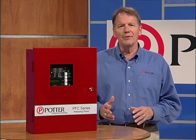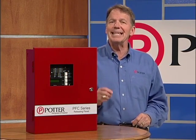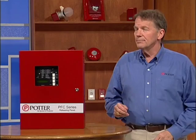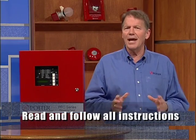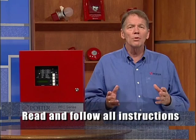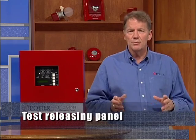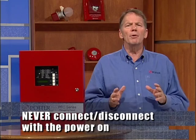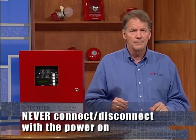Now that you understand the types of systems releasing control panels manage, you're ready to begin the installation process. Here are some general rules that you'll want to follow. First, last, and always, make sure you read, understand, and follow all of the instructions included with the releasing panel. Before leaving for the job site, test and program the panel completely to familiarize yourself with it and ensure proper operation. Remember, never connect or disconnect wiring for circuit boards with the power on.